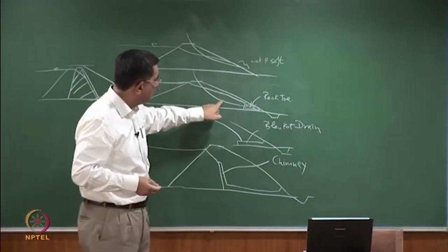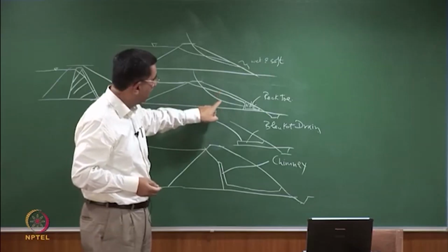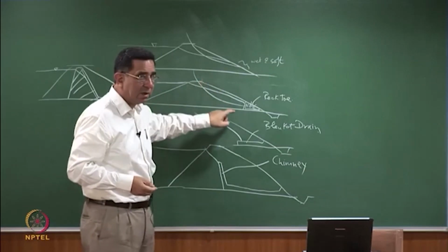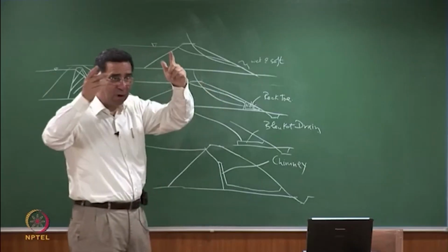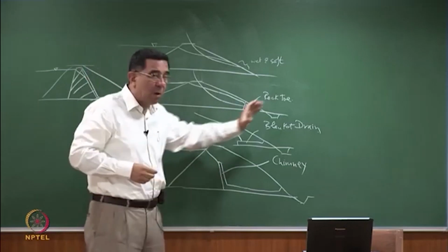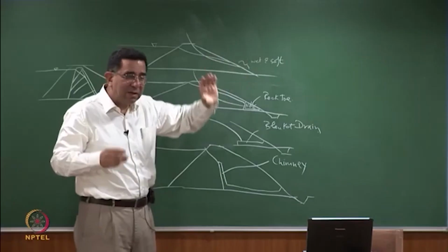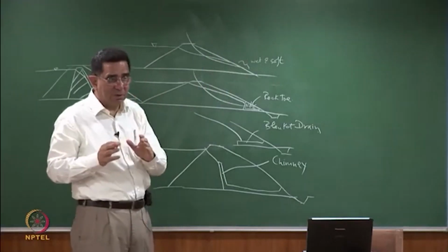What is my pore water pressure going to be determined by here? That's the phreatic line, and that's the point on which the stability depends. So it's about the phreatic line on the top. Seepage from below will change the amount of seepage that is occurring. Piping on the other side, yeah, that's a different issue altogether. That's not a slope stability issue.